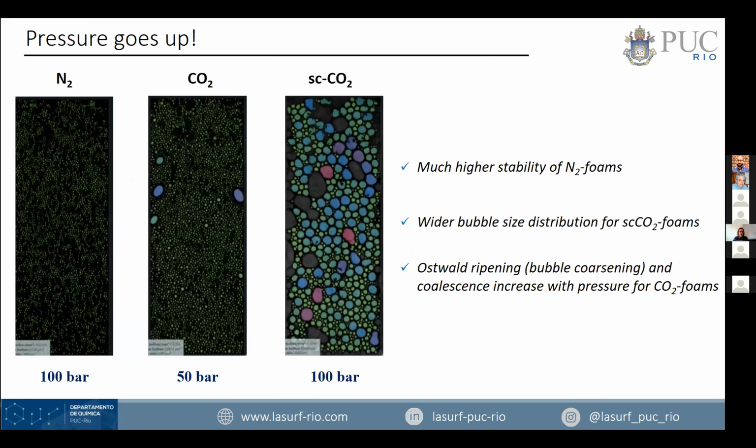And then going directly into the stability of the foam, this CO2 foam in the pore network, you can see that while using only surfactant, we obtain very few, very thin lamellae through the micromodel. Then when we add the silica nanoparticles, stabilizing the foam, we can have a larger amount of lamellae.